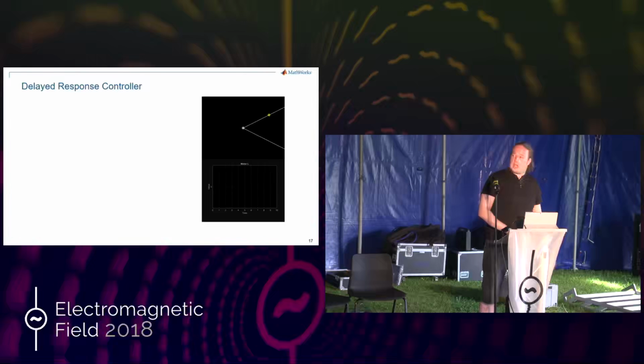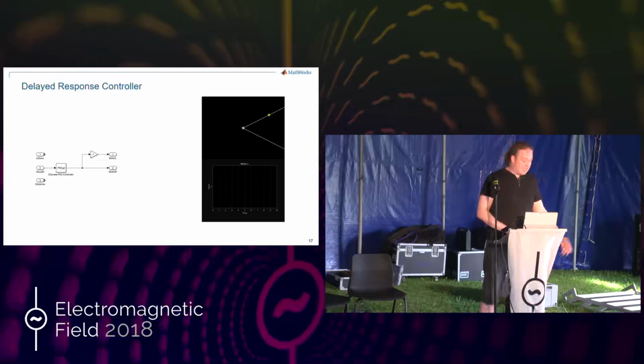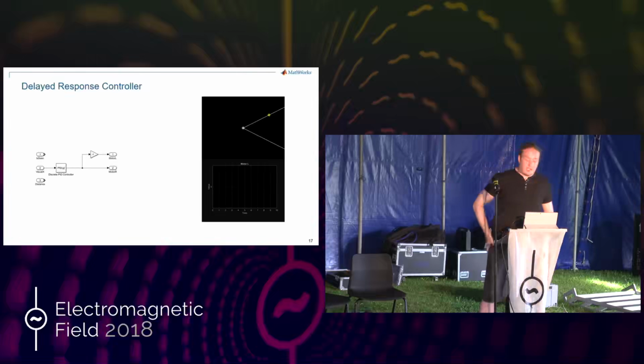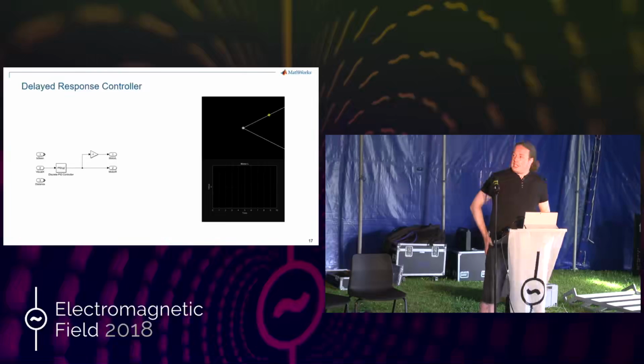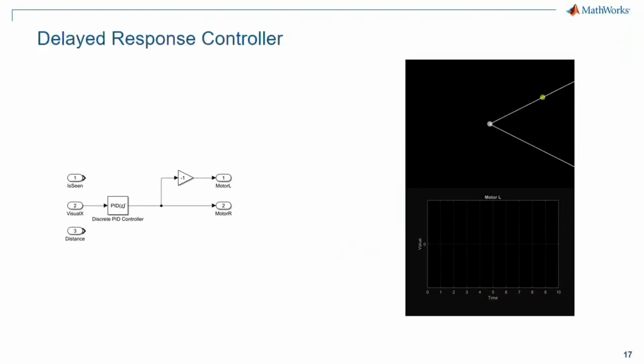If you do a bit of searching around, the thing that most people do is they use this thing called a PID controller. It stands for proportional, integral, and derivative. So imagine the further away you are from your goal, the more force you want to apply. But if you're not moving, you might need a little bit more force, so you want to be increasing the force over time until it starts to move. And finally, you want something which puts brakes on. So you want something based on the derivatives to say the faster it goes, the more force you want to apply in the opposite direction.